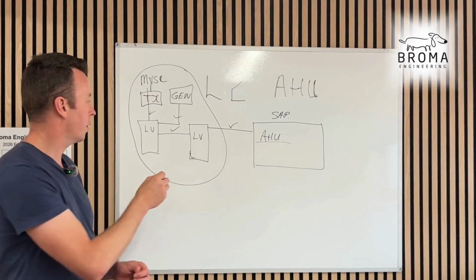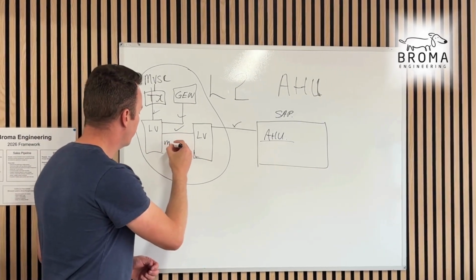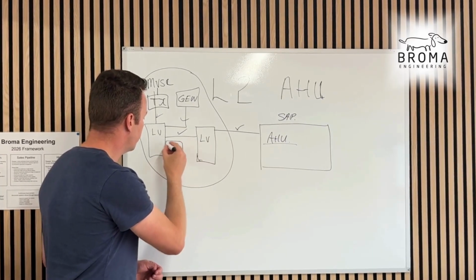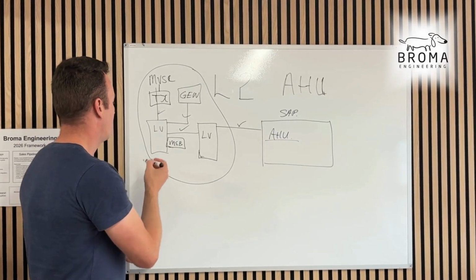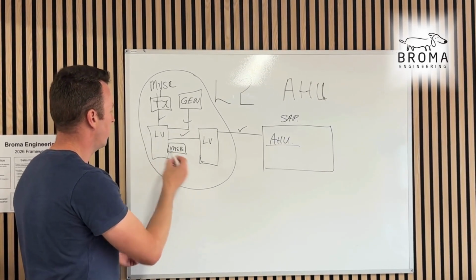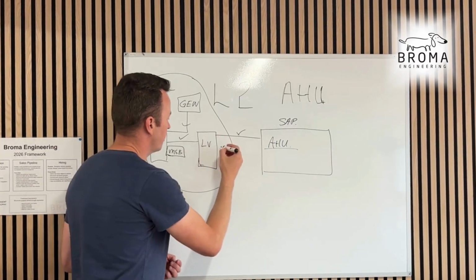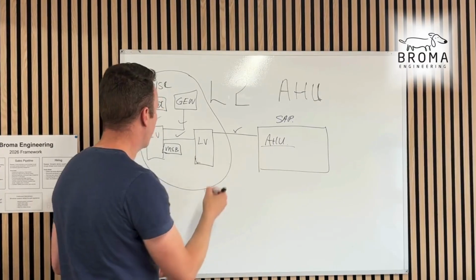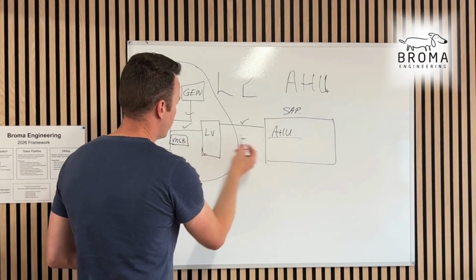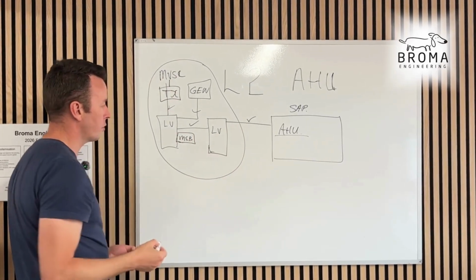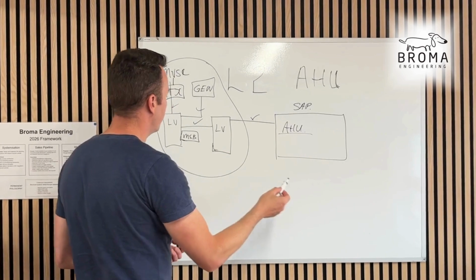And that's why the main switchgear, I'll call it the MSB here, plenty of different names for that, we'll just call it the main switchgear or the main switchboard. This is the hub of everything, really. This sometimes is called your house mechanical or mechanical distribution. This might be down near the AHU, or it might be in the switch room with a cable going to the AHU.